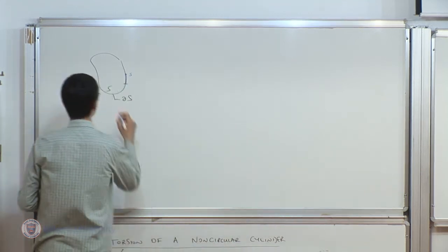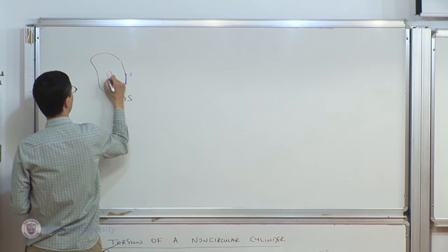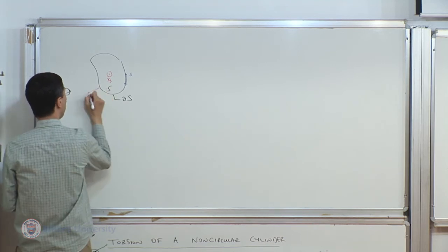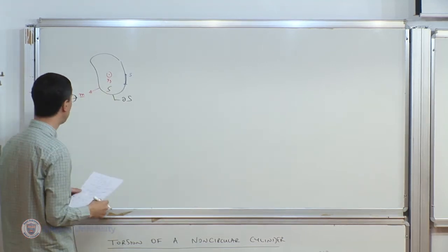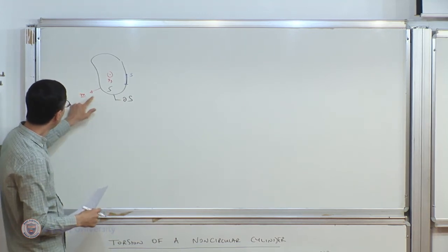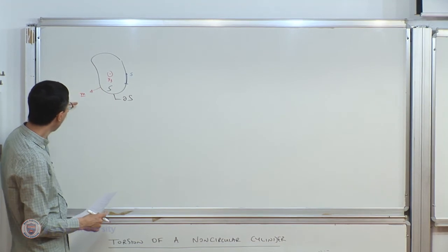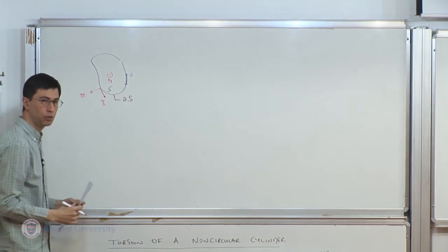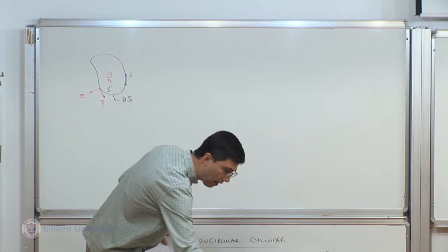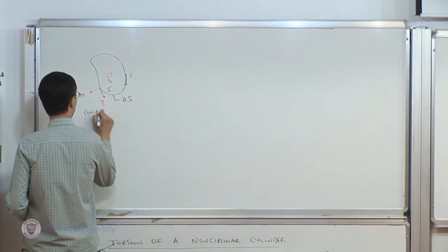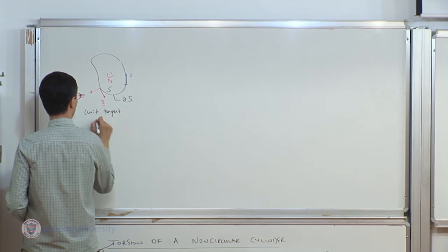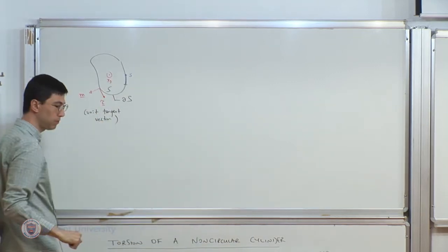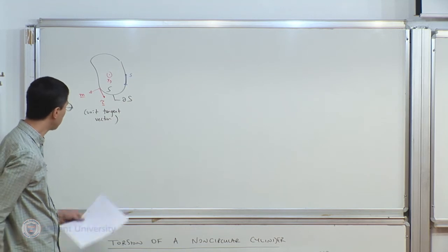And out of plane direction is the x3 direction. And the normal that I'm trying to characterize in order to calculate eventually what the traction is, it's m here. And I will introduce yet another vector which is not normal, but tangential to the boundary. I'm going to call it a vector tau. And this eventually will also be a unit vector. It's the unit tangent vector, and it is tangential in the direction of counterclockwise rotation.